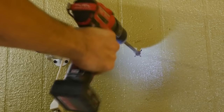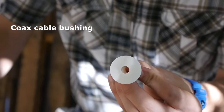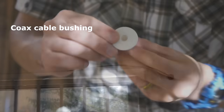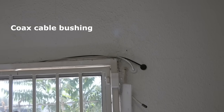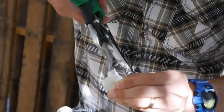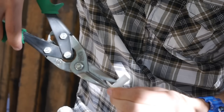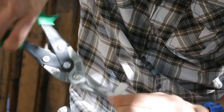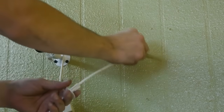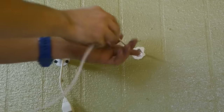First, drill a hole in the wall that's just big enough to fit the cable. Before you run the cable through the wall, you'll want to use a Coax cable bushing. This is going to seal up the hole you just made, and it also makes it look a lot neater. These Coax bushings are designed for fitting wire only, and then you crimp on the connections later. We're not going to do that today. Instead, we're going to cut a slit into the bushing so we can feed the cable through with the connection and all. Then attach the bushing, feed the cable through the wall, put a small amount of caulking around the hole, and slide the bushing through, and that's it.